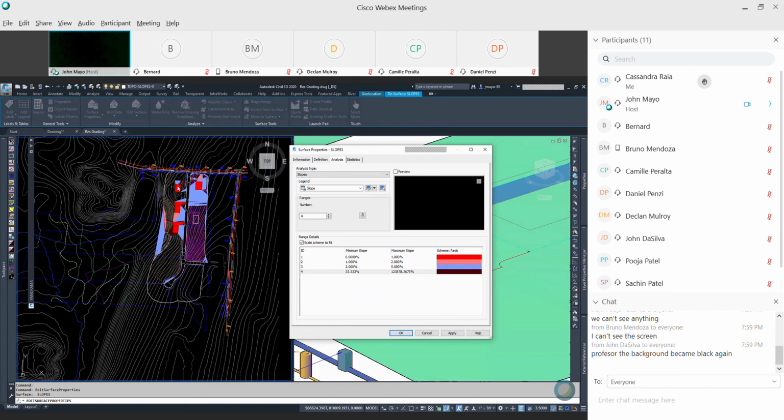And if you notice, all my basement floors are red, and that's good. I expect it. I have flat basement floors. So that doesn't shock me. There's no error there. But I have some red over here. That would be something to worry about if that was within my limit of disturbance. When I fix up my border and put that on later, that will go away. I've got some areas right here that are much greater than 1 on 3.